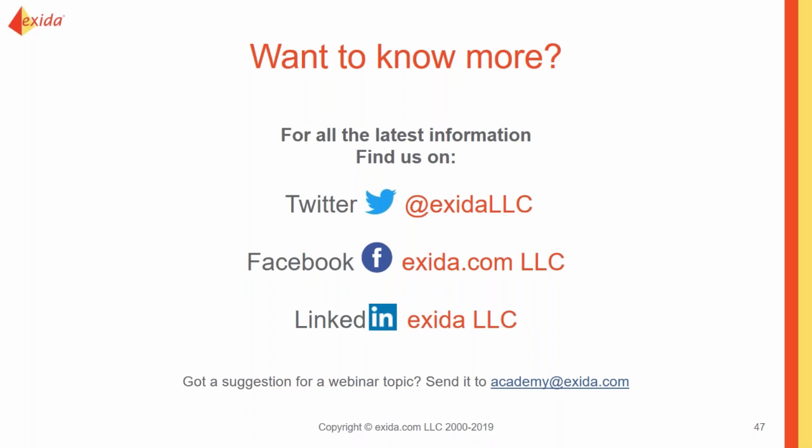The next question: if the end user uses a certificate that's based on 2H, will they still need to provide the proven in use justification? No. If you have something like an exida certificate and it says that this product in this environment has already been approved per Route 2H, your homework is already done. That's the benefit of buying those certified products. You just take it. You still have to do your calculations to make sure that you're going to hit all of your risk reduction targets, but you don't have to do the proven in use justification yourself.